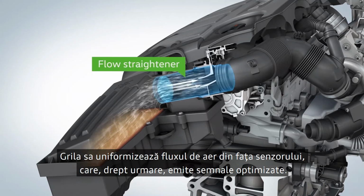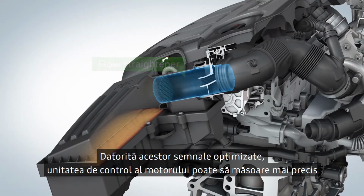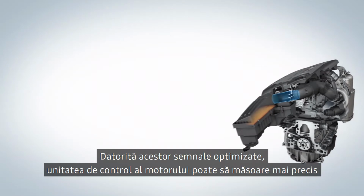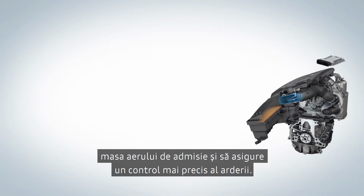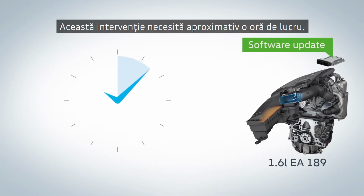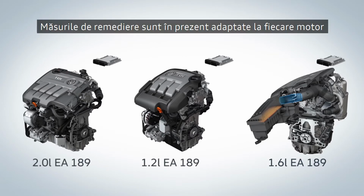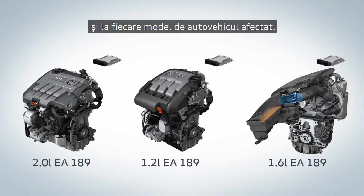Its grid calms the flowing air in front of the sensor, which delivers improved signals as a result. With these improved signals, the engine control can more accurately measure the mass of the intake air, and this ensures a more accurate control of the combustion. This refitting will take approximately 1 hour. The refitting measures are currently adapted to each engine and each affected vehicle type.